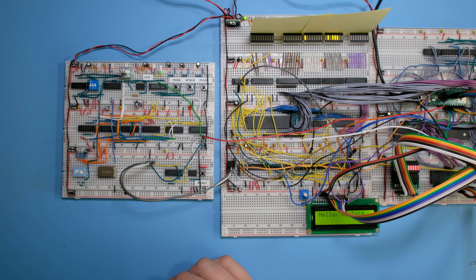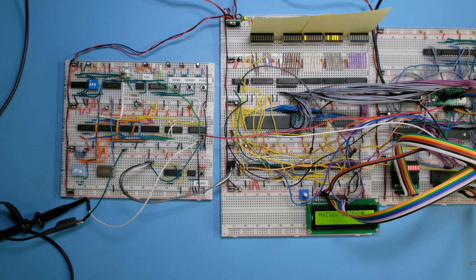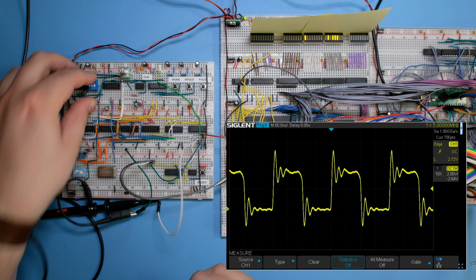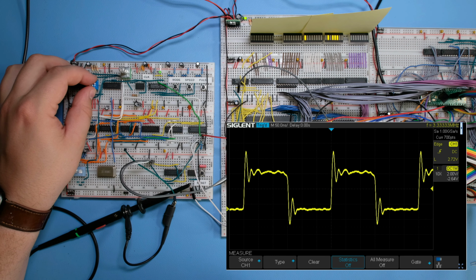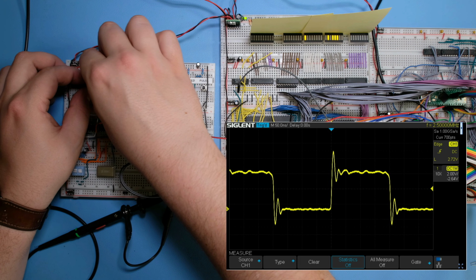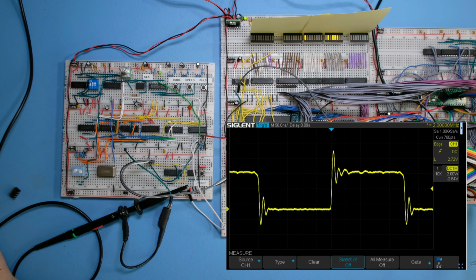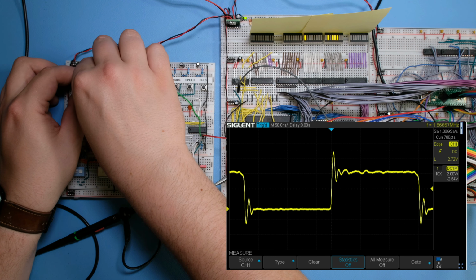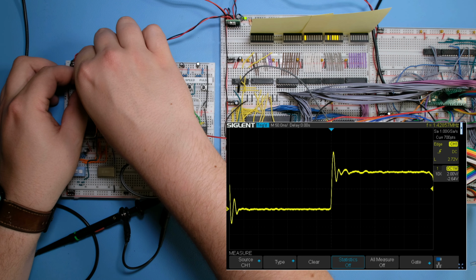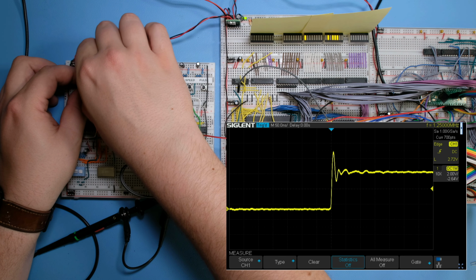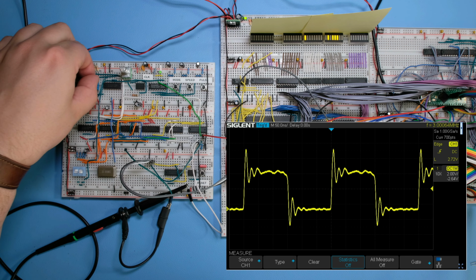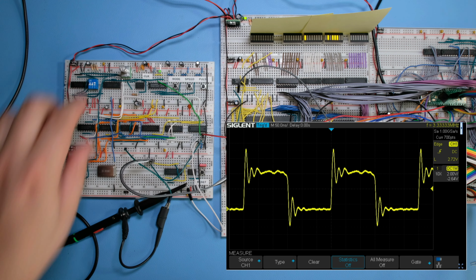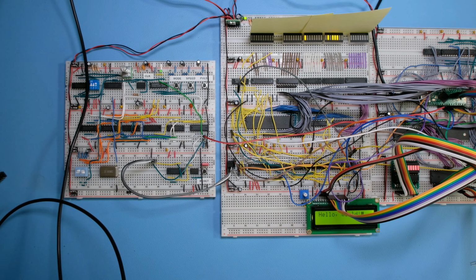Let me bring in my oscilloscope just to check the values. Okay, so when everything is at 0, it's 5 megahertz. 1 is 3.33, that's correct. 2 is 2.5. 3 is 2 megahertz. Then we go to 1.67, 1.43, 1.25, and 1.11. Awesome. So this is all still working. And I'll go back to 3.33 megahertz, which is the safe frequency here.